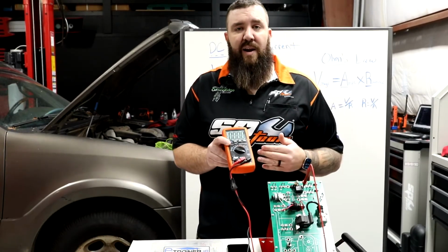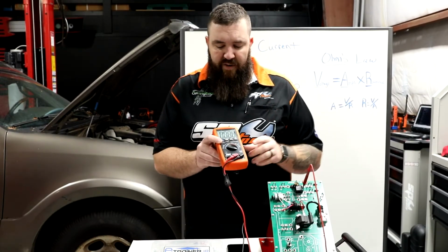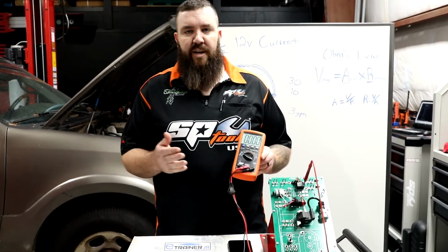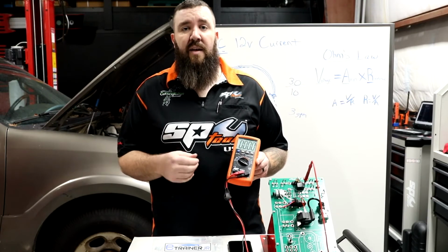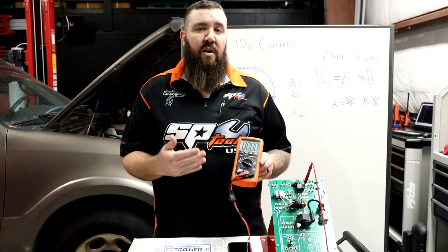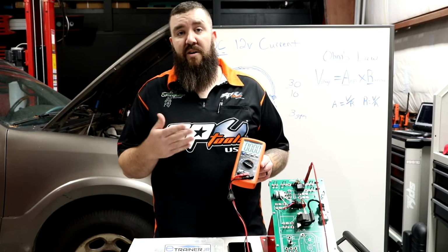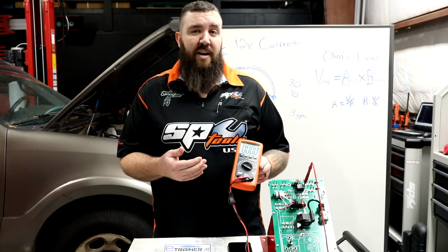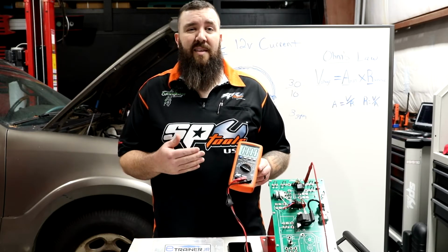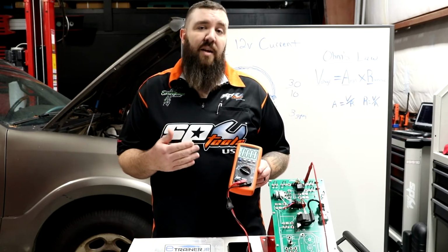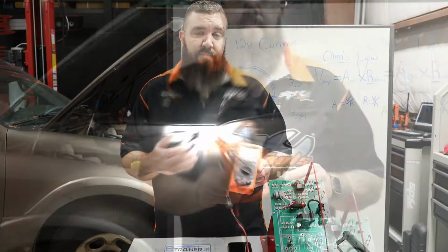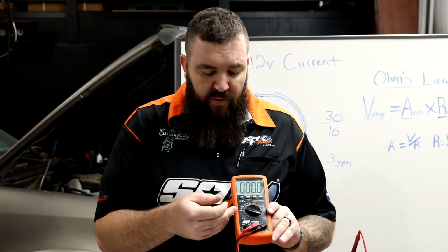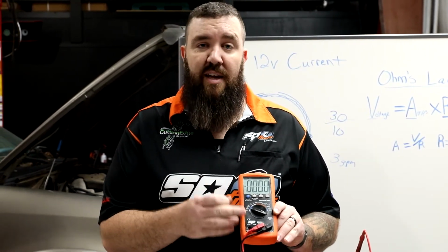Pretty easy, self-ranging. It's going to be automatically functioning in that version, and digital multimeters can come in all different shapes and sizes, cost amounts and values. I would recommend at least getting an auto ranging multimeter for the guys that are just starting out in things. Yes, they might not be the cheapest things to get a hold of, but they're going to give you the easiest factor of learning when we're going into DC voltage. So in today's video, the only function that we're going to be really focusing on is going to be our voltage functions here on the meter.